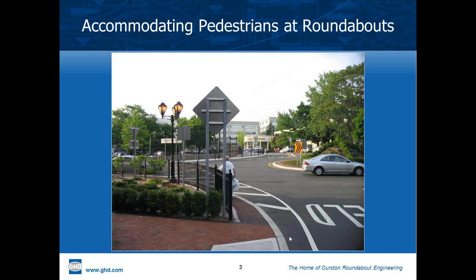So what's shown around here is a white edge line, and there's a pedestrian walking in front of the railing. So there probably shouldn't be a railing in this space here, but the point of this slide is just to indicate that, you know, roundabouts and pedestrians, we have to guide them to the right place to cross and make it safe to cross and provide good visibility. So sometimes the handrails, and they're quite popular in England and in the London area where roundabouts are popular with a lot of pedestrian traffic, they tend to have to gate them and guide the pedestrian to the safe crossing locations.